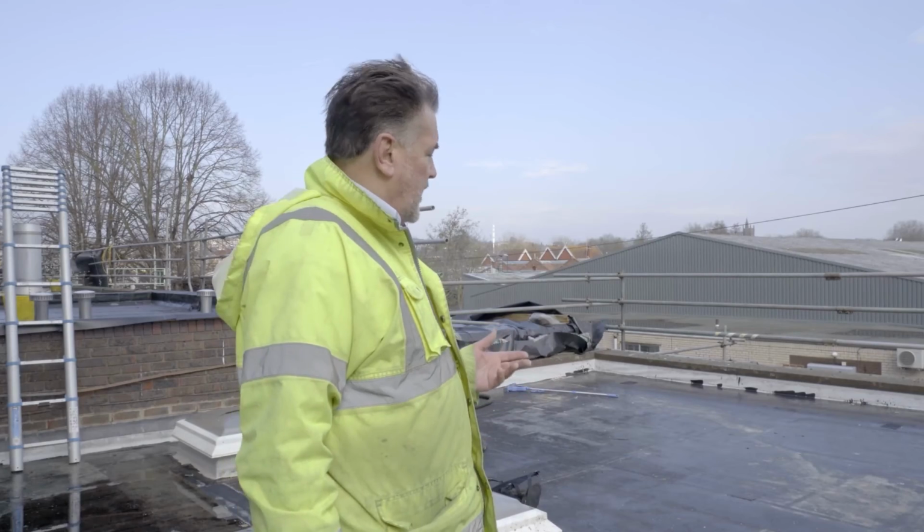Okay, so I'm going to core test this roof to try and determine what the existing build-up of the roof is and find out what type of deck's in place. I'm looking around and I'm thinking, I know from experience that anywhere adjacent to the outlet is probably going to be the place where there's the most amount of water. So I'm going to go over here and cut a hole now.